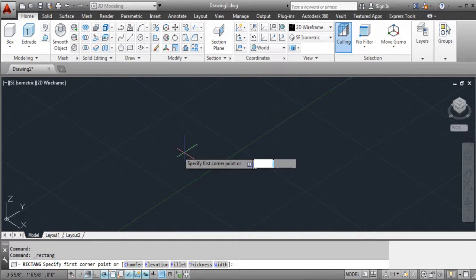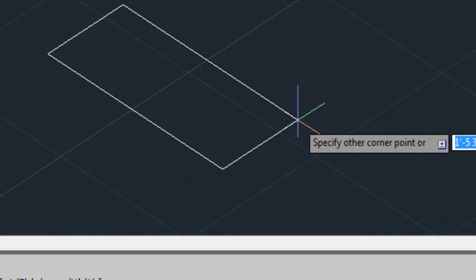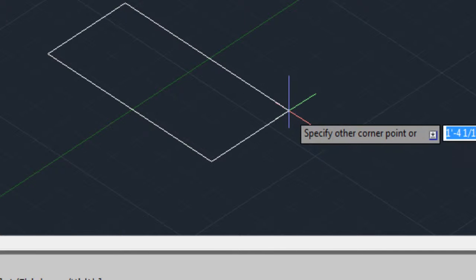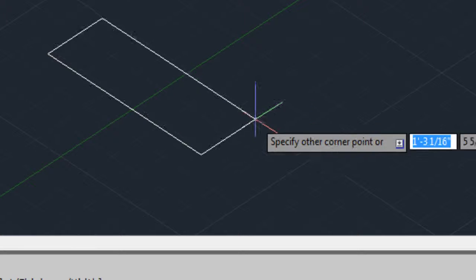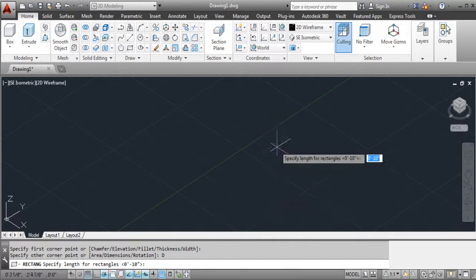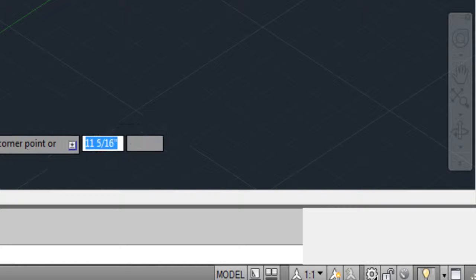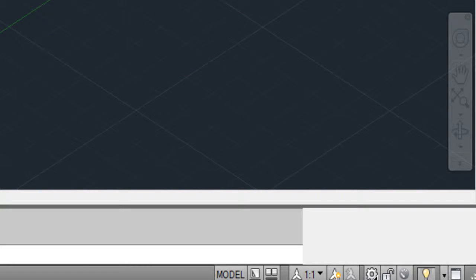The first drawing you're going to be doing will look like this. You'll want to start with a rectangle, and you'll want to make sure that your dimensions are correct, and you'll want to select down here at the bottom, you'll want to select dimensions. Okay, so if we wanted this rectangle to be, let's say, the length will be 8. Okay, so we'll do 8 inches, and we want the width to be 4 inches. It will draw a rectangle for us that is 8 by 4.